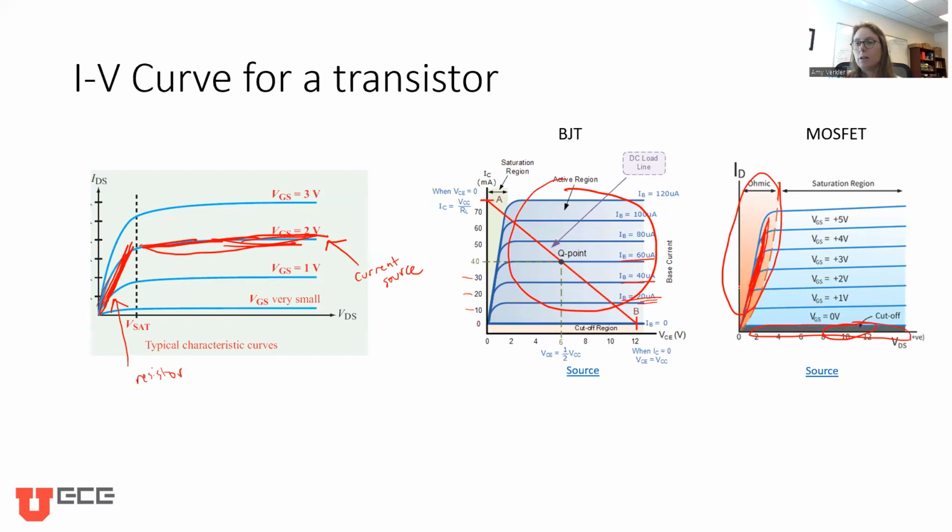And so depending on what transistor you're using in what region, we have different names for it, right? So the MOSFETs being used as electronically controlled switches, they call this region over here the saturation region because they're not working with it. Similarly, the BJT being used as a current amplifier calls this region over here the saturation region because that's not the region they're working in. So notice they use the same term to represent different regions in their specialized IV curves.